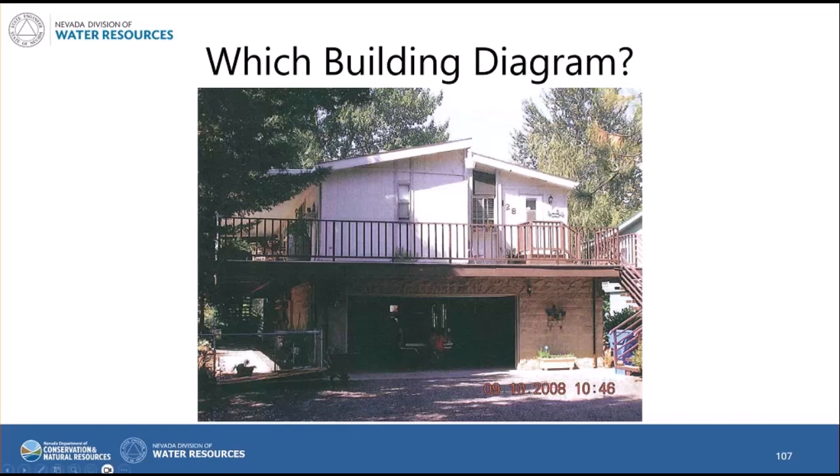Scattered responses. This one tends to be tricky. This is actually a diagram 7. It could confusingly look like a 6, but a 6 would be piers, posts, or piles, with wood frame walls or maybe breakaway walls or some other framing. This isn't framing. This is a full-story masonry enclosure. So this is the diagram 7.